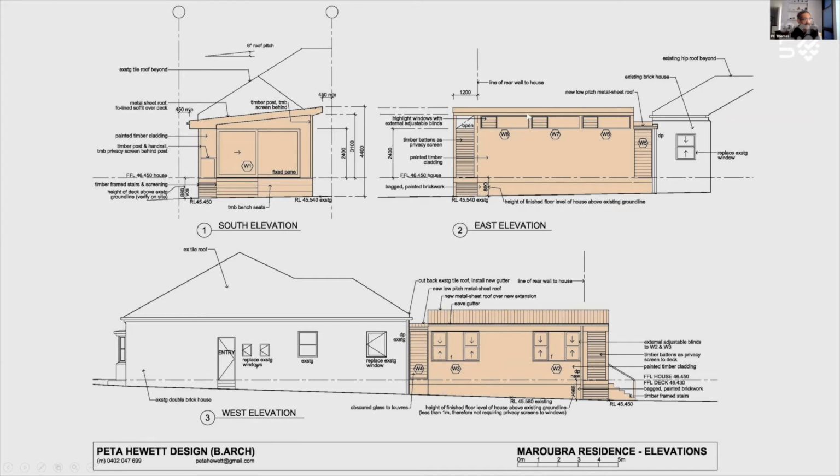And then on the west elevation, in Australia, we have this beautiful thing called double hung windows, which you won't find anywhere in Europe because they leak. But they're great because they don't swing in or out, and when you've got a tight site, they're very good. And you can open them: when you open the bottom and the top, you get passages from which you can encourage natural ventilation.